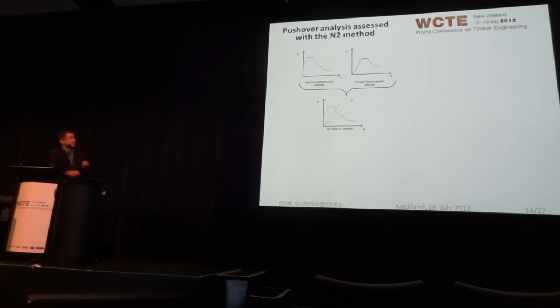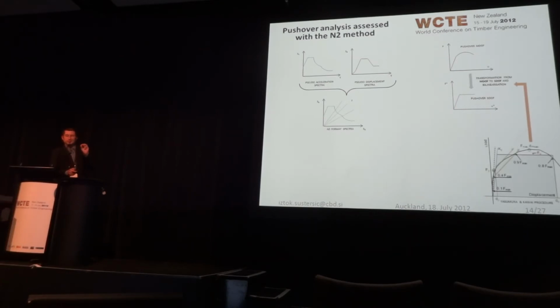We have the displacement on the x-axis and acceleration on the y-axis. And the vibration periods in this case are characterized by the linear functions that you can see here in gray. Now, keep in mind, displacement on x, acceleration on y. If we make a pushover analysis of a multi-degree-of-freedom system, therefore a building, we get displacement on the x-axis and forces on the y-axis. Then we transform that pushover curve to a bilinear curve. Here is where we made our slight modification. We weren't using the typical bilinear procedure that's prescribed in Eurocode. We made some modifications that we have found to be more proper.